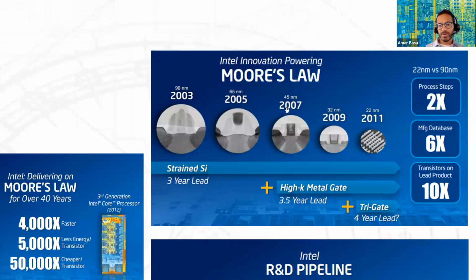So by 2007, they were working on 45 nanometer node sizes. By 2009 and 2011, they were down to the 22 nanometer node sizes. Now here, in order to make these generations of transistors work, Intel had to go to a high K metal gate, like a high K dielectric, in order to make sure that the threshold voltages were large enough. And then here, we talked about this in class the first time, is that the on-off ratio of current became quite poor with the standard 2-dimensional transistor.